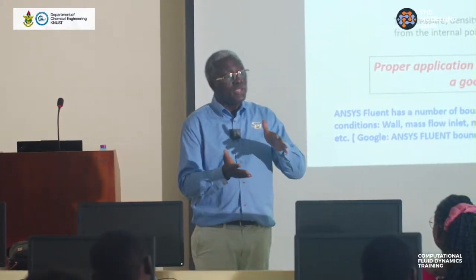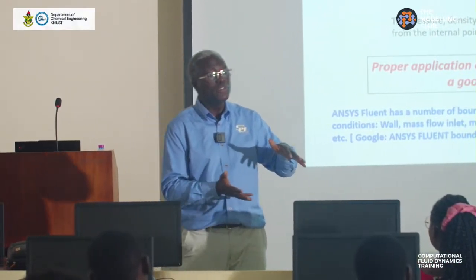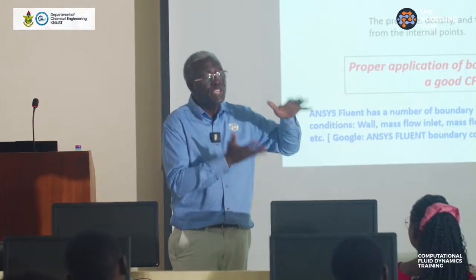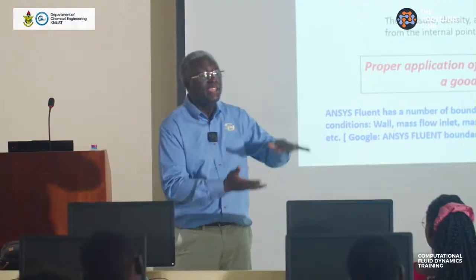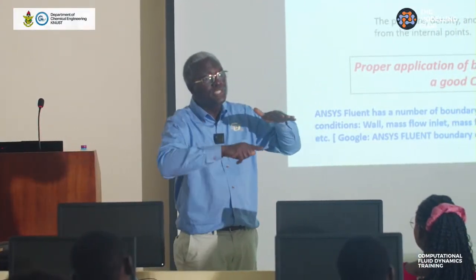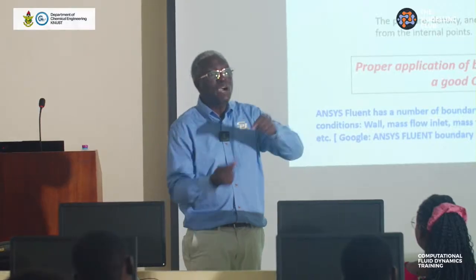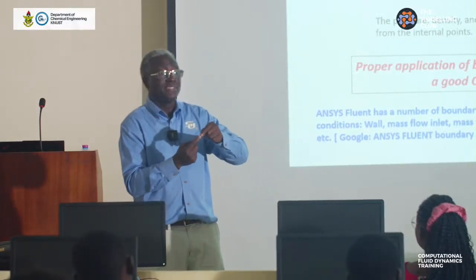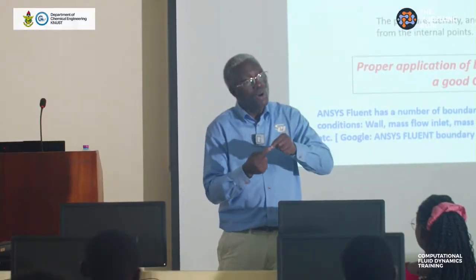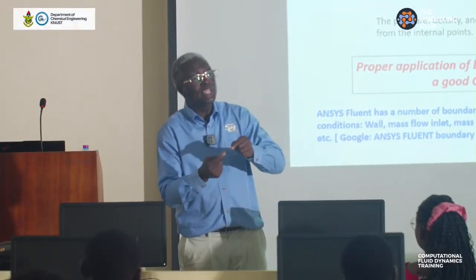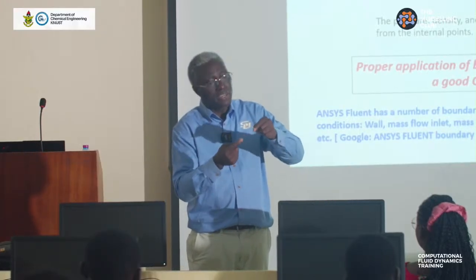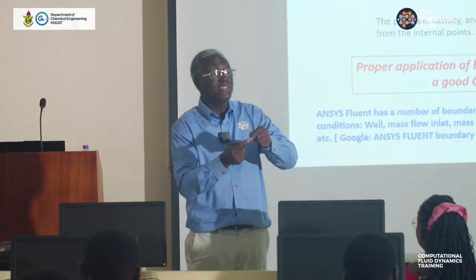In which case, yes, you have to come up with equations for each of the phases, for the air and for the water. Now, there will have to be a constitutive equation that couples the two together. I haven't talked about that, but in multi-phase flow you have to come up with constitutive equations that couple the interface of the two together.